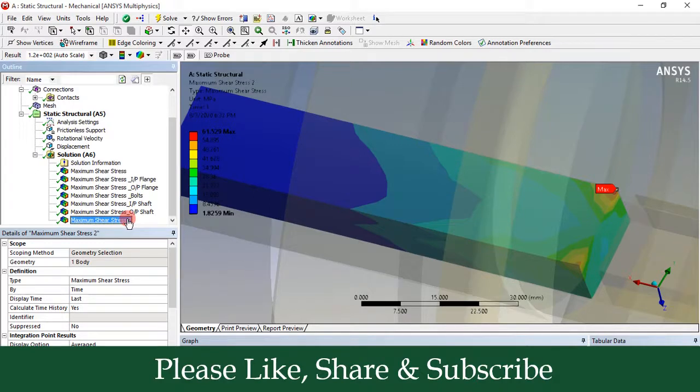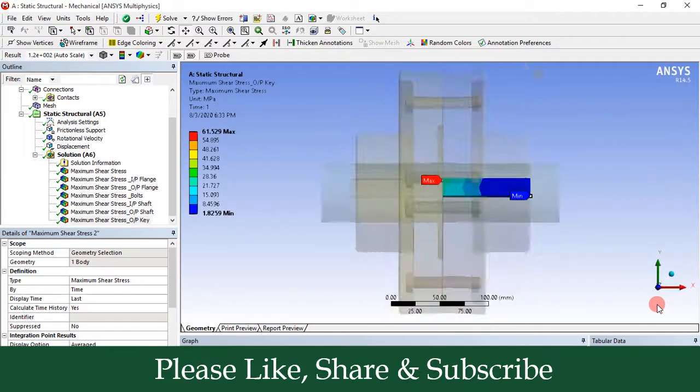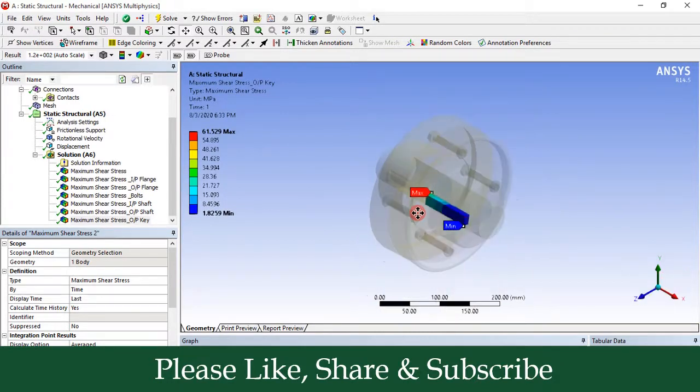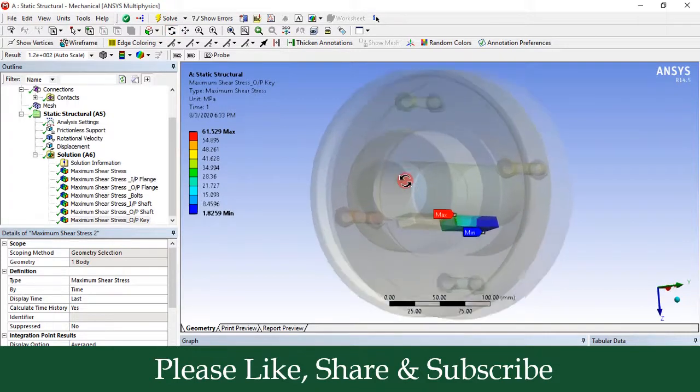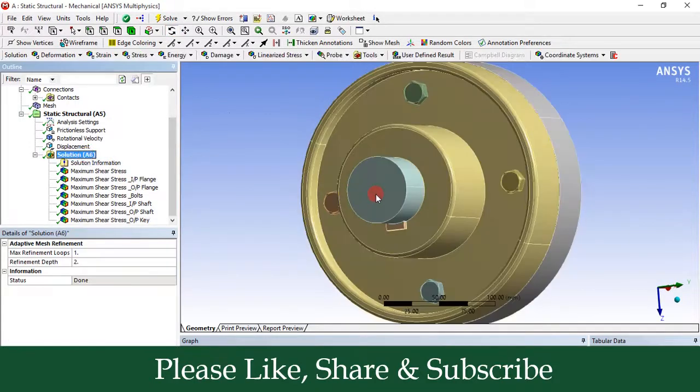Now just rename this parameter. So we will write here, this is for output key, that is the key of output shaft. Now you can similarly check the maximum shear stress in the input key. So you have to rotate this model, click on this solution, go to the body button, click on this key.